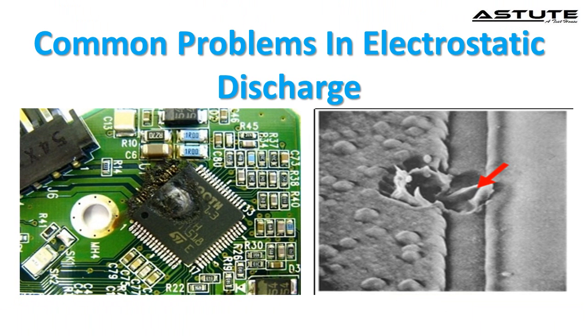Common problems in ESD immunity of devices are given below. All materials like insulators and conductors are sources of ESD. Human touch is only sensitive to ESD levels that exceed 4000 volts. Troubleshooting electronic equipment or handling printed circuit boards without using an electrostatic wrist strap. Placement of synthetic materials, that is plastic, styrofoam, etc., on or near electronic equipment. Rapid movement near electronic equipment. Due to the human body model. Due to the machine model. Due to the charged device model. Due to the field-induced model.